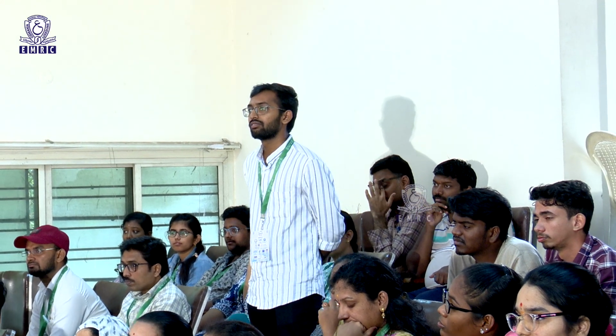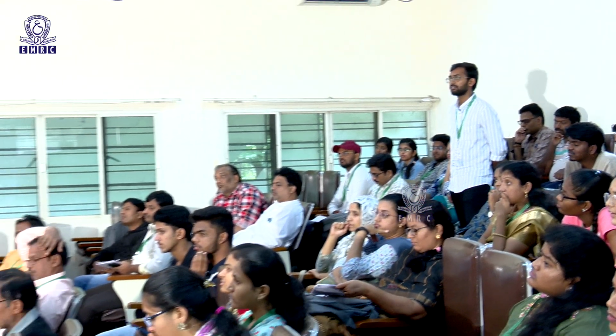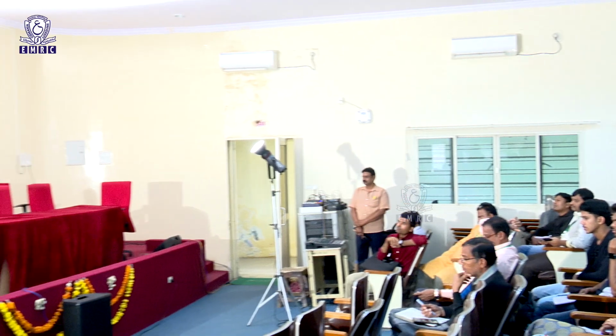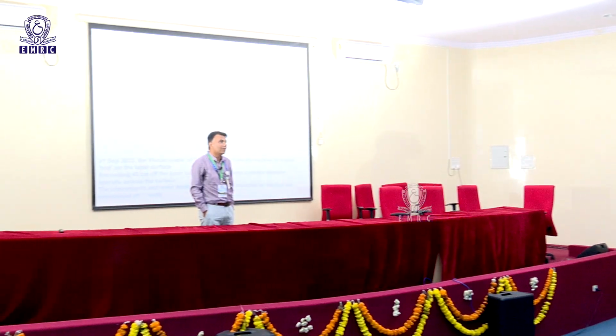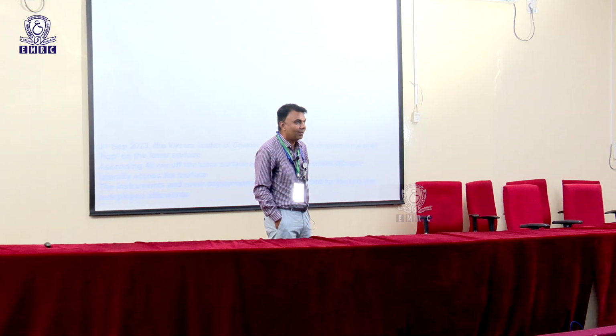Of digital filter, regarding memory based or lookup table based? That is a good question. For onboard, we'll prefer lookup table based. But in general, it depends upon the resource utilization and what type of filter it is. Suppose you have a very high tap FIR filter. FIR filter, I am talking about very high. Let's say, as I mentioned, in a digital filter we have a 1500 tap filter. Suppose you have such a high order of filter, then memory based will not do the job. Then you have to go with a LUT based approach. Then it will solve your issues.